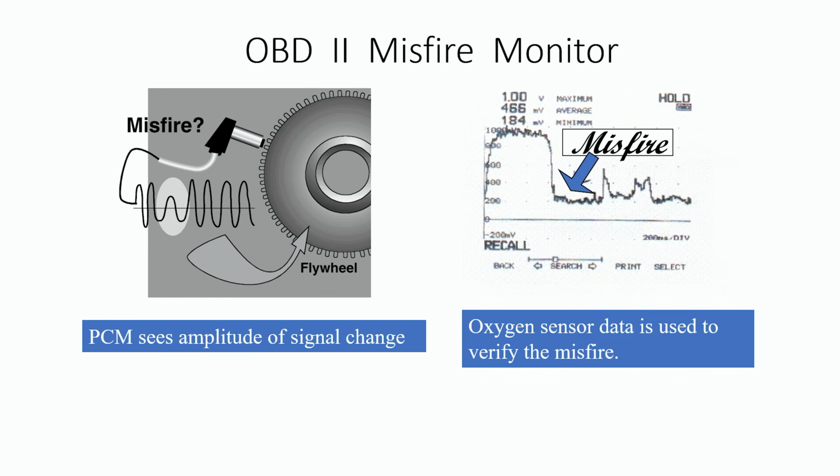So that mixture should go lean on that particular O2 sensor. If it's a 4-cylinder, it's only going to be the pre-cat one. If it's a V-design engine, you're going to have 2 pre-cat O2 sensors, so whichever side of the engine had the misfire. So you saw the little waveform of how that looks in real life when a misfire is actually captured.